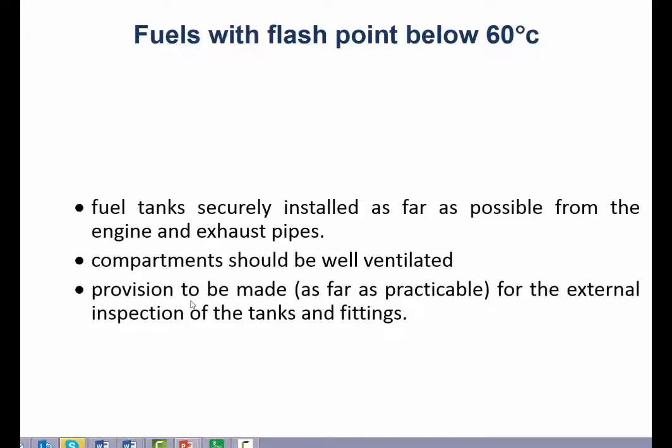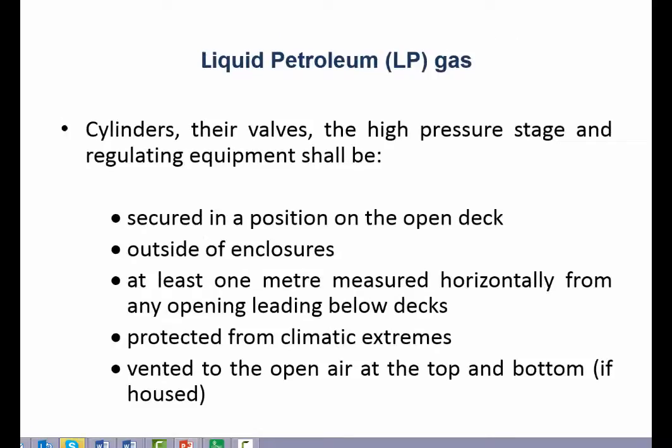And then provision for external inspection of tanks and fittings. So we need to be able to access it to do inspections. LPG gas cylinders, their high pressure stage and regulating equipment shall be secured in a position on the open deck. Okay, so we can't have it inside the accommodation, outside of enclosures, and at least 1 metre measured horizontally from any opening leading below decks.